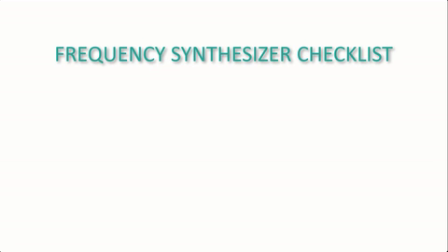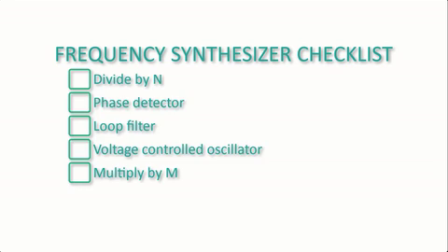Okay, one might imagine that at this point, we have everything we need to build a frequency synthesizer after all. We know how to build an integer frequency divider. We have a couple of different phase detector designs. Averaging filters are a dime a dozen. And we've seen at least one voltage-controlled oscillator design, and since we learned the trick of putting a frequency divider in the PLL feedback loop, we know how to multiply frequency by an integer. Great! Now we're ready to design the M/N frequency synthesizer we want.